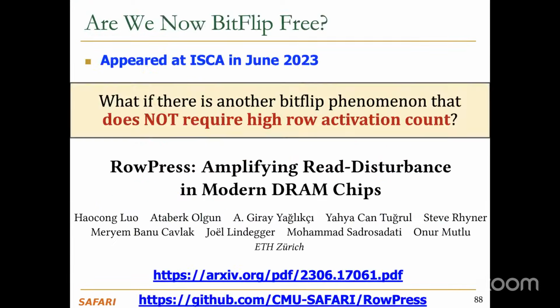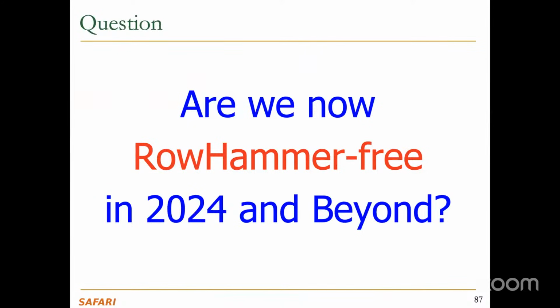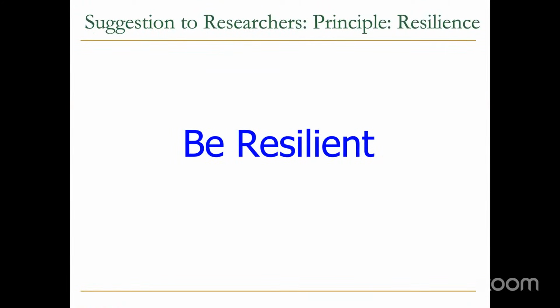Okay, this is a good place to take a break, I think. We're going to have more of this discussion, actually, for reviews. But I wanted to discuss this because this SMD idea, I think, is a very nice, principled way of designing the interface. Because the principle is basically very simple. There are multiple principles. The memory controller should do what it's good at. The DRAM chip should do what it's good at. And the interface should minimally be changed to allow those two functions. That's the idea. And that's the principle. And this principle apparently disturbs a lot of people.